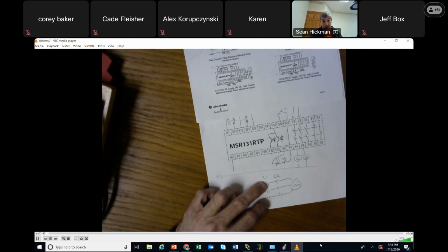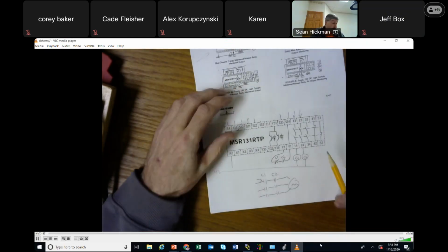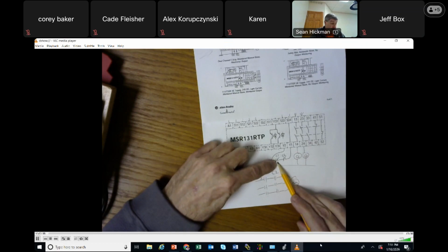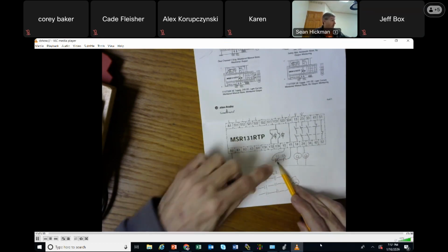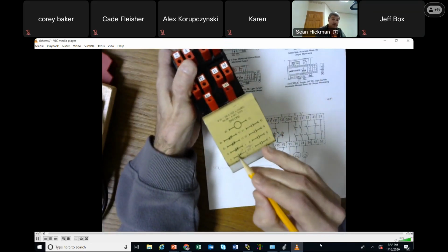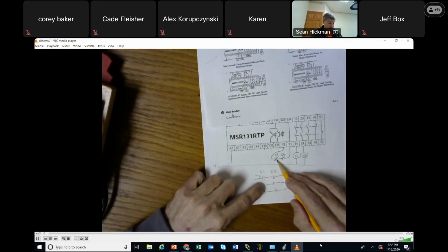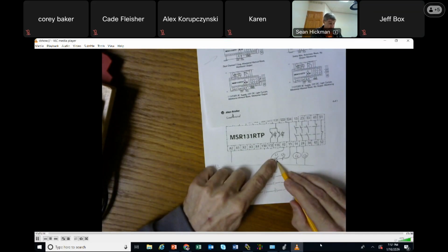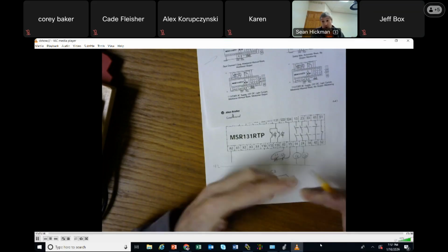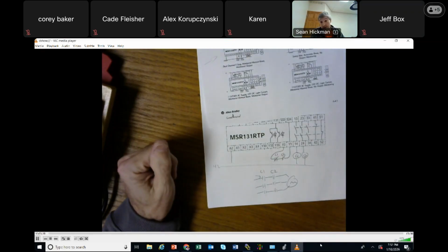That's a safety relay. Okay, so what the safety relay is checking is to say the contactor is off because it's a closed contact. And so we're looking at, you know, number 3 and 4 right here, and it's closed. Well, if one of these is burned on, then that's going to be open, and then this will not reset. This safety relay just will not reset, just like the way that I showed you with my little trainer.